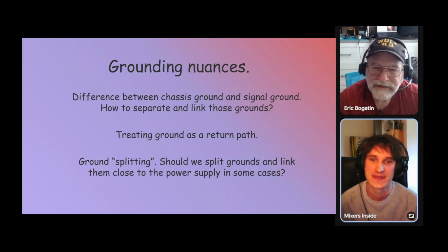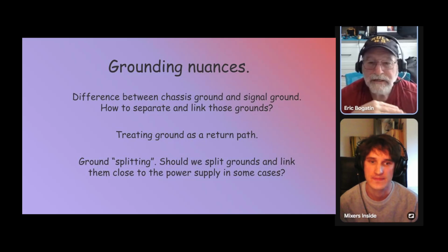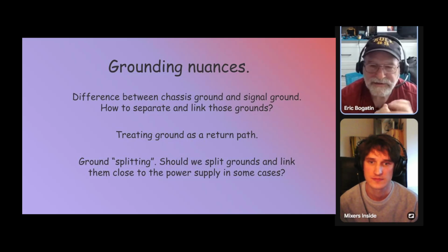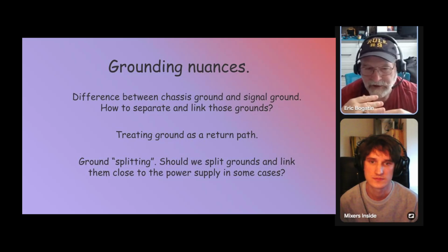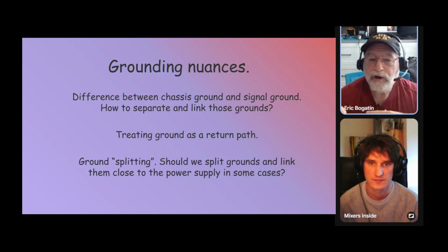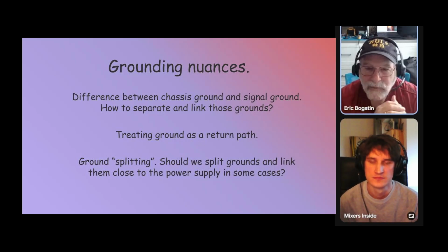Great. Perfect example. And you're right. In general, the recommendation is never split a ground plane because of the potential problem that if any signals cross the split plane, that introduces a huge amount of noise. And so generally, in most designs, there is never a need to split a ground plane, and there are potential problems that can arise if the ground plane is split. But there is that one exception, and that's the exception you identified.